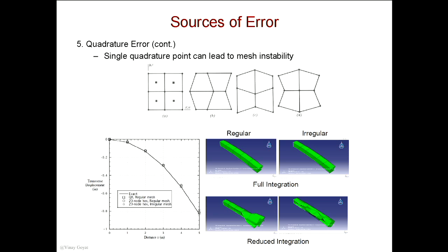And so if I look at a mesh and apply bending to this mesh, you're going to get stuff that looks like this. Nonsense, basically. Here you can see that with reduced integration, with brick elements, there is some nonsense when I apply bending loads to this beam. You can try it at home. Take C3D8R elements.